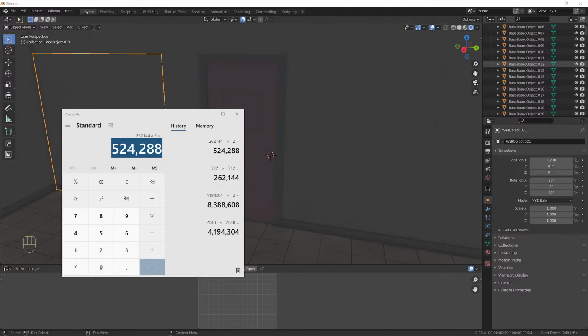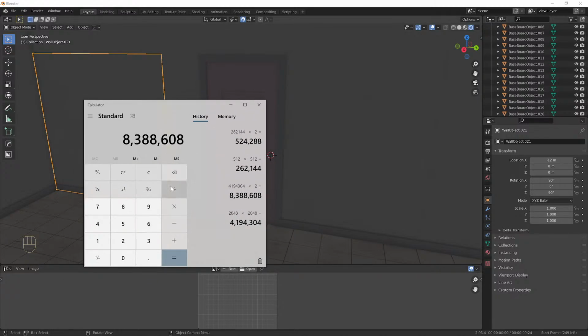So I could just look at the squares and figure this out, but it's just so we can really break down what we're working with here. So press Control V here. So we have this 8 million from our 2K, 2 times 2K maps. We divide that by our two 512 maps and divide by that number. So we get 16. Basically, we're only using 1/16 of our space, right?